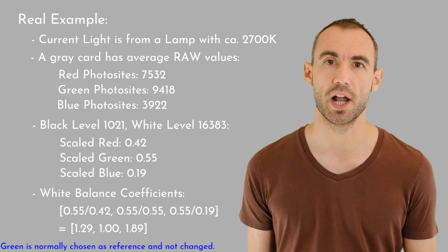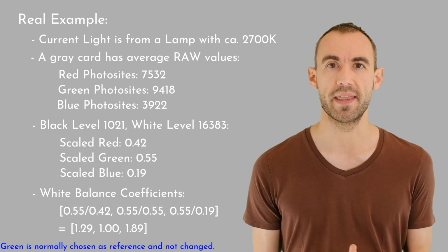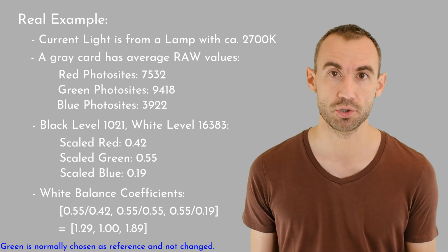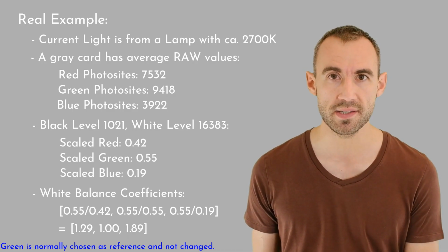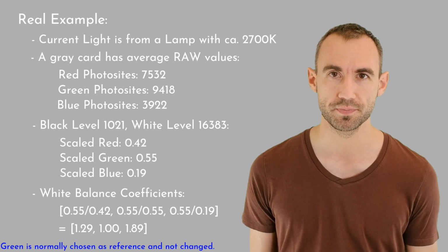And those values are chosen such that when the light that's currently considered to be white shines on the sensor, then the red, green, and blue components should all give the same value. So for white balancing, we multiply pixels by a number. And as we've just seen before, we can multiply our raw image by some value without messing up our vignetting correction. So applying the white balancing step before the vignetting correction is not a problem.